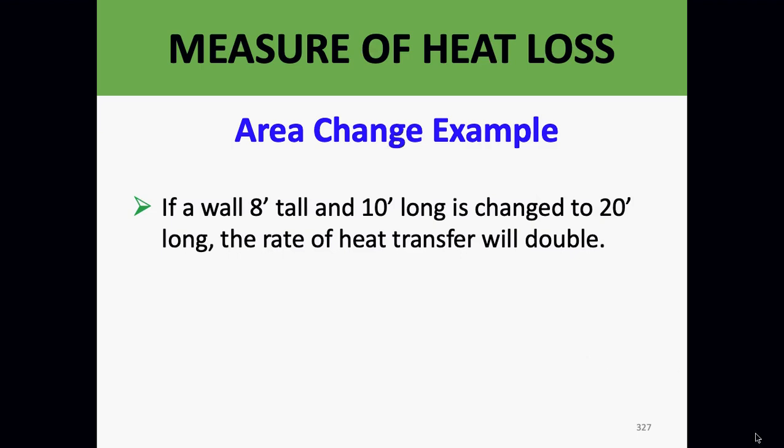Again, we have to remember our formula. The Q, and that's a Q, sorry, equals U times area times delta T. Okay, so anytime we increase the area, we increase the heat transfer.